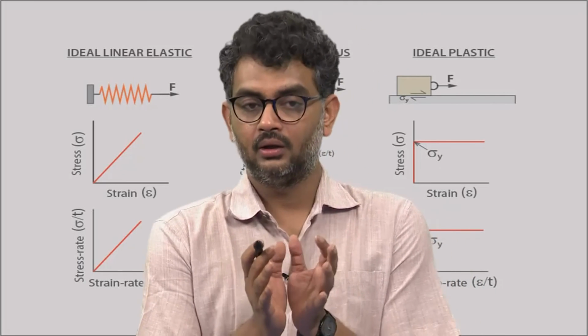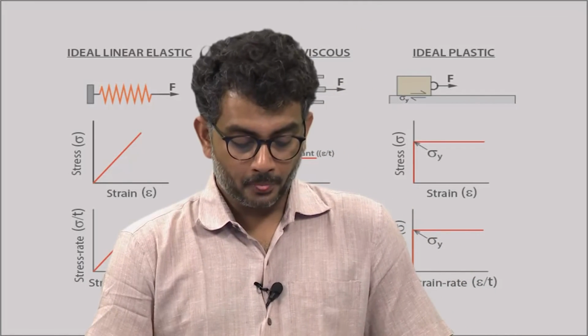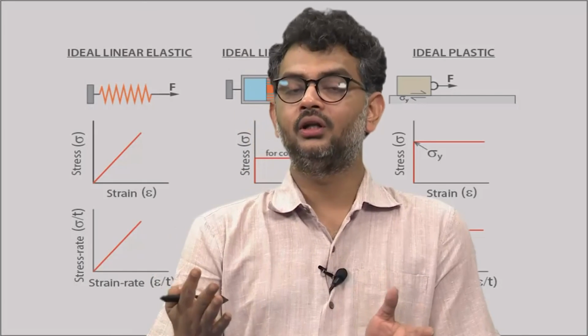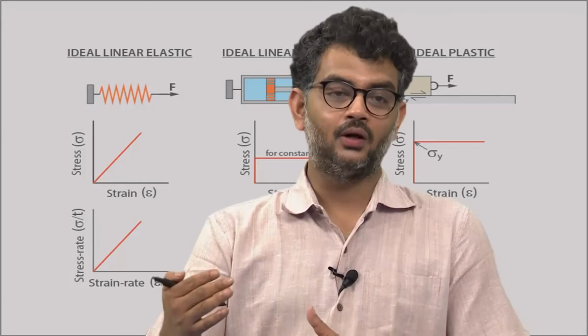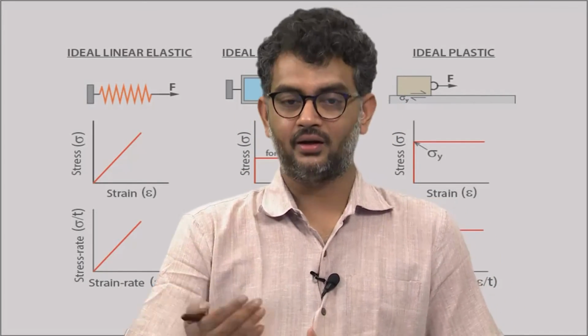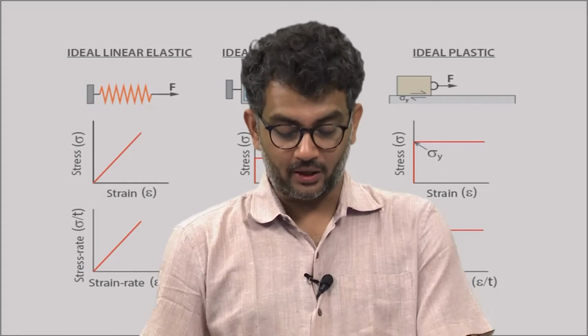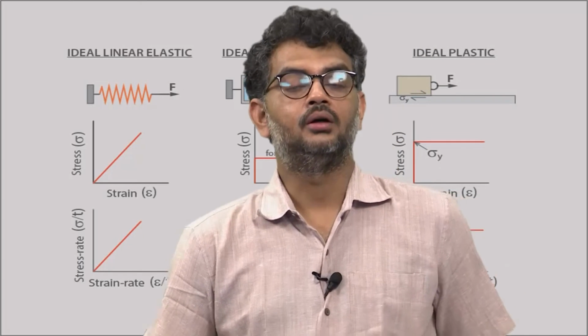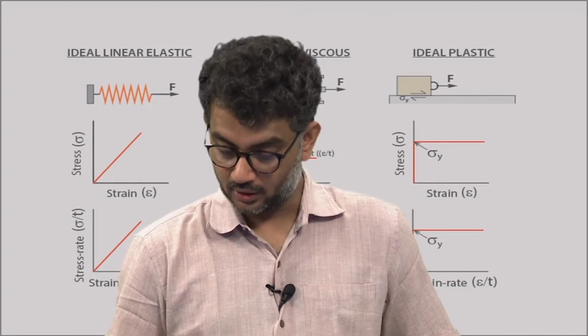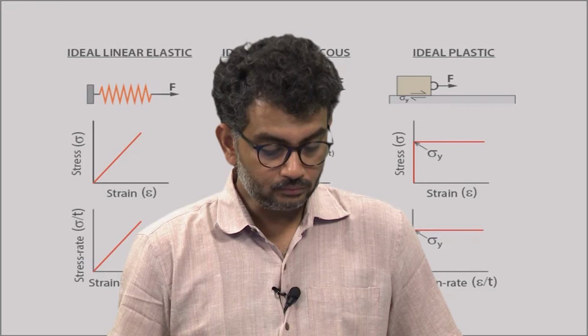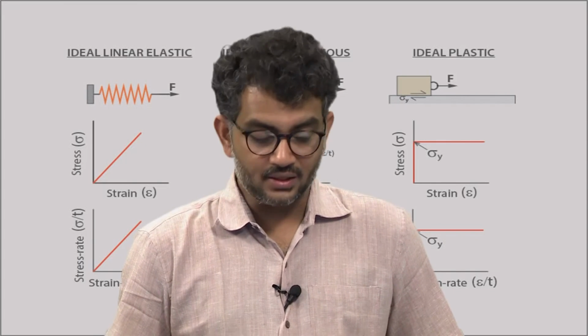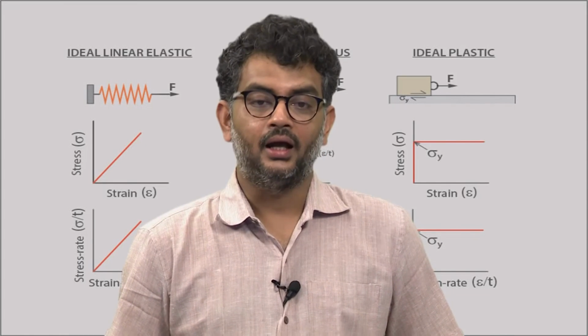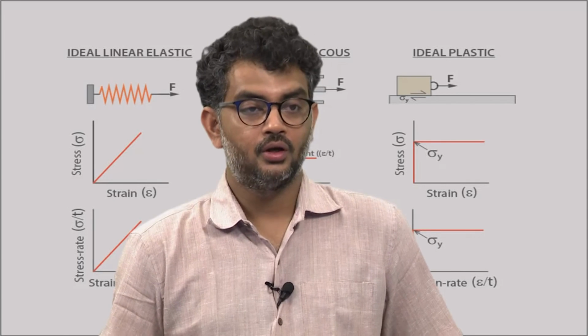You remember the mean stress and all other issues. And when we are not dealing with the normal components, that means the off diagonal components where shear stresses are acting, then simply by considering i not equal to j, you can get the shear modulus of the elastic material. Now, with this I would stop, and then we will move to the next topic, viscous rheology.